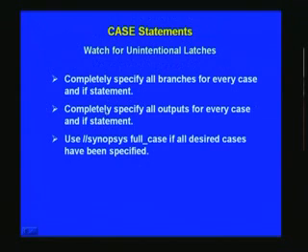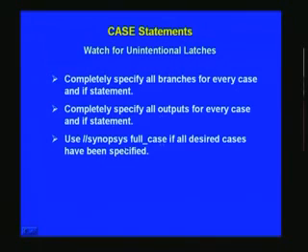Similarly, completely specify all outputs for every case and if statement. We have seen this also in the always block earlier using case, where we had 8 outputs, D0 through D7, and we took care at every case statement that we reset all other unwanted outputs other than the one which we wanted to set high, right? That's what it implied here. And use full case if all desired cases have been specified.